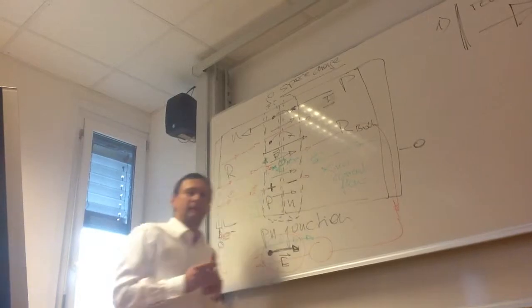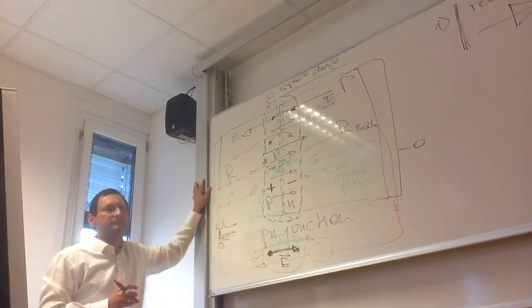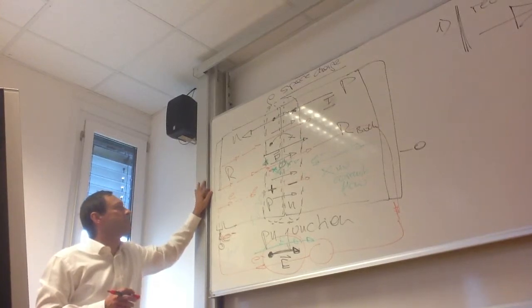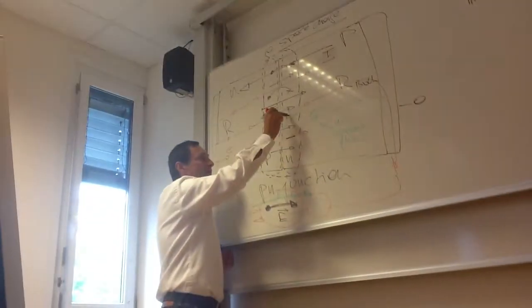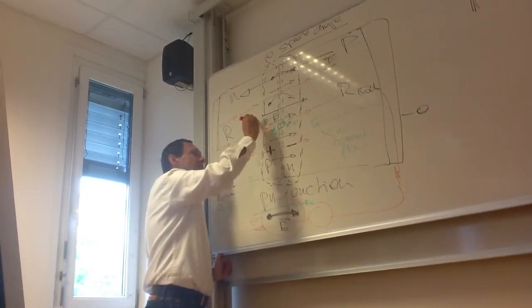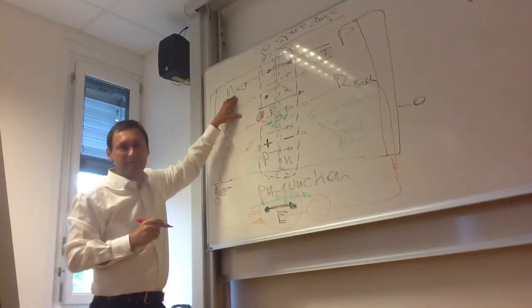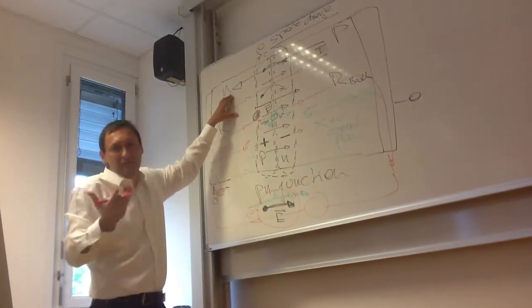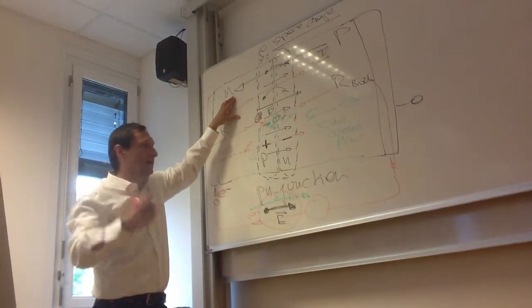What is happening is that the photoelectrically generated electron goes to this side here, in the N area, and in the N area it can freely move, because there are no holes that will suck up the electron.